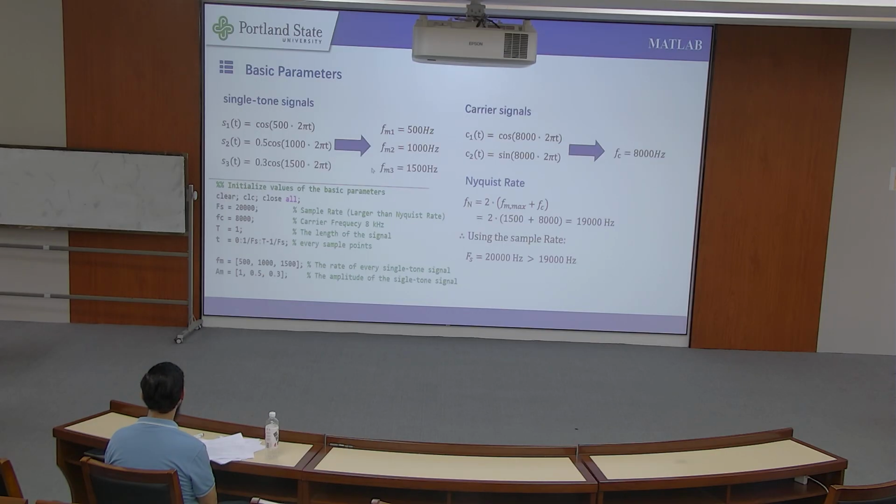This is where the magic happens. This ŝ(t), pronounced as hat, is the original signal after passing through a Hilbert transform. Think of the Hilbert transform as a universal phase shifter. It takes every single frequency component in our original signal and shifts its phase backward by 90 degrees. We then multiply this phase-shifted signal by a sine carrier.